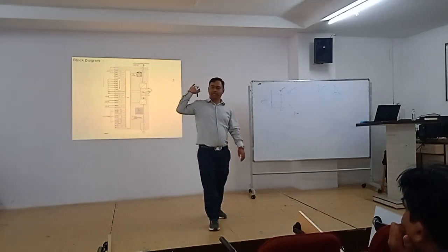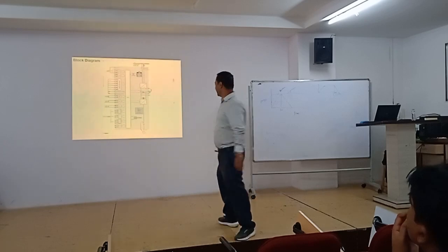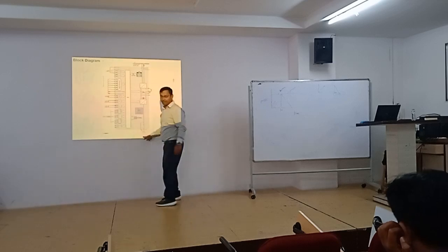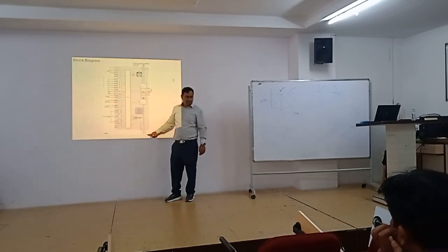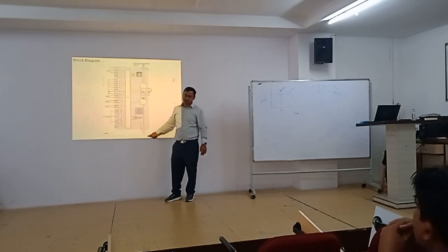So this is actually a special type of VFD in which you give a single phase supply and the output is three phase. But definitely the output is only 220 volt three phase. It cannot make 440 volt. But we are getting a three phase supply here, and the motor will work with the three phase, no problem.